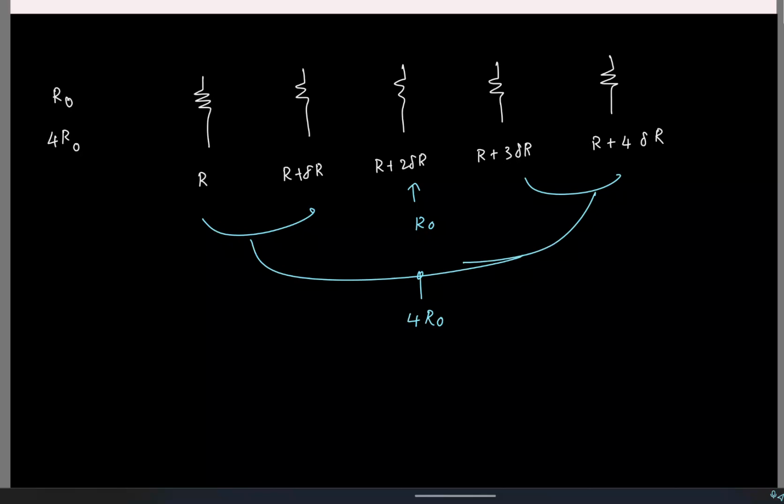And if you think about it, the logic is you try to keep the centroid for all the elements the same, right? All the elements have the same centroid. So this is called common centroid layout. Again, this is coming from plain logic and common sense. There is not a lot of technicality involved. So if you do this common centroid layout, any variations or mismatch due to linear gradient completely get cancelled.